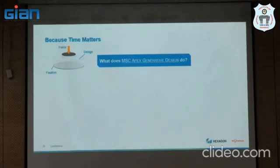Trying to understand what we mean by optimization. How does any optimization tool work? It is not specific to one tool, it's about the technology. Currently I have a component, can you see here. For any optimization, I need one component, one force acting direction or one loading condition, and one fixed point, or you can give fixation as another geometry, or you can fix a body.